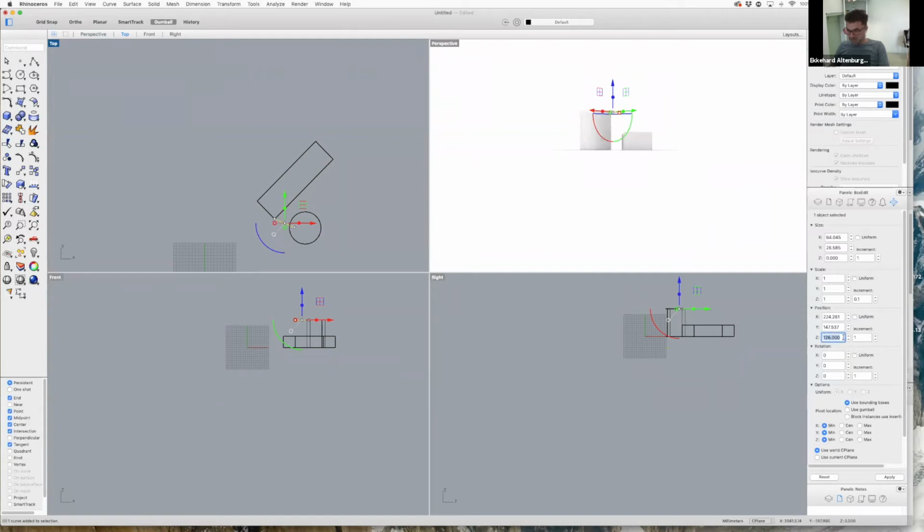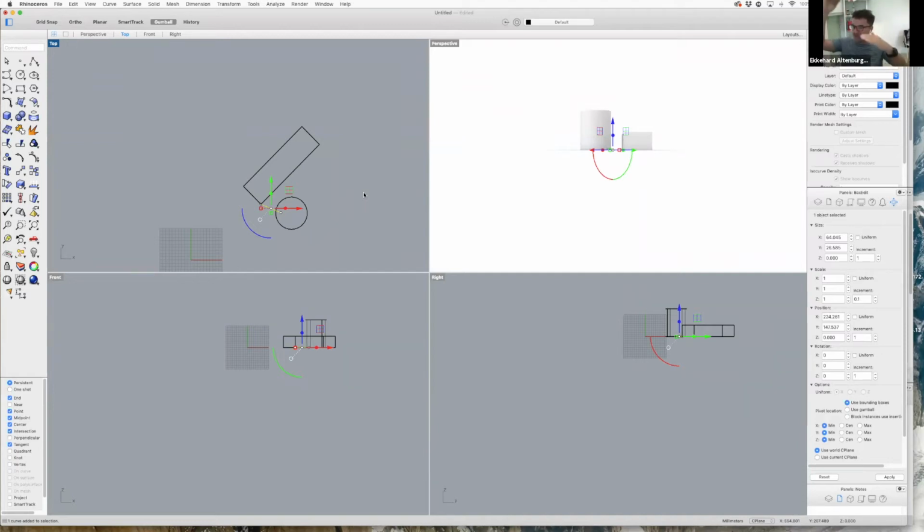I go to this field, I type in where I want it. So 0 means on the ground floor. So basically that's where you stand, you know. So this is the ground floor and I apply it here, press apply. So at the moment I have all my objects lined up on the ground floor. Imagine everything falls down on your desk. So this is your drawing desk, the ground floor. And then, you know, if you want to build something up, you can move them in the Z direction upwards.